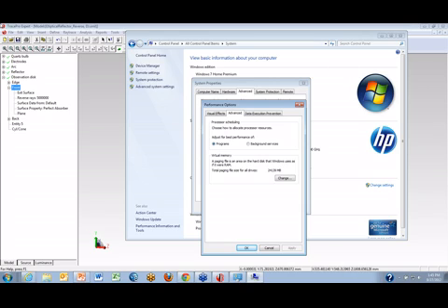Okay, I guess my last comment was, when you were talking about defining the number of rays to trace, make sure that if you're doing an irradiance map, you're looking at the number of rays actually getting to the irradiance map as opposed to the number of rays you're starting from the source, because that's really where you need to get enough rays on that irradiance map.